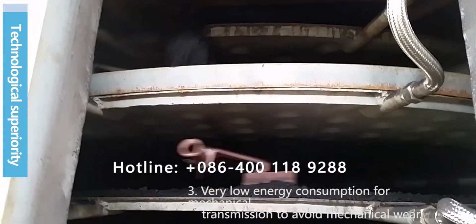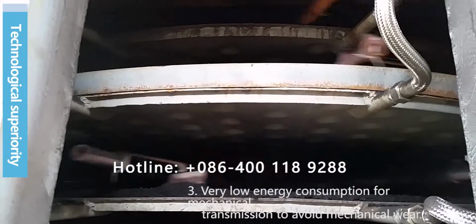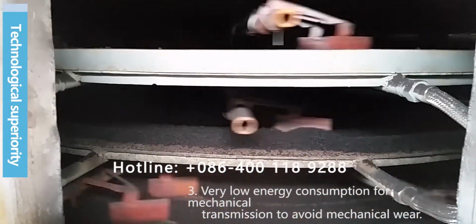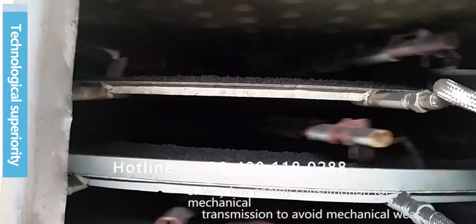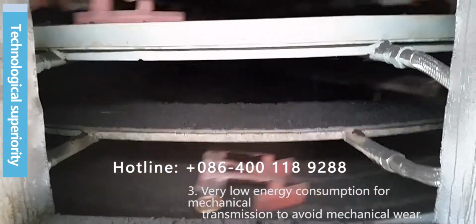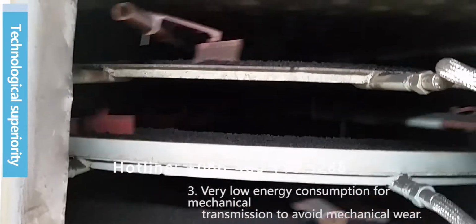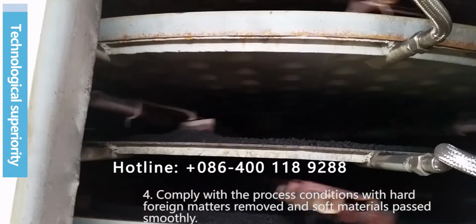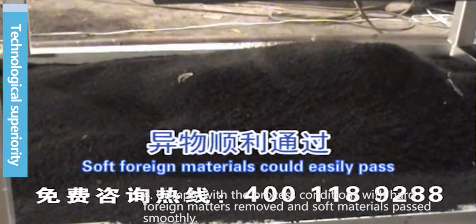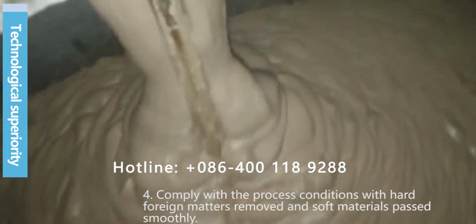The electric power consumption of granulation is only 1 to 1.5 kilowatt per ton of sludge, and is only 2% to 3% of traditional dryers. Practically, after a half-year operation, the disc surface's painting has shown no abrasion. The drying process is more efficient, removes hard and soft contaminated objects preventing damage to the dryer, and has advantages in drying high-protein, sugary and greasy kitchen and oily sludge.